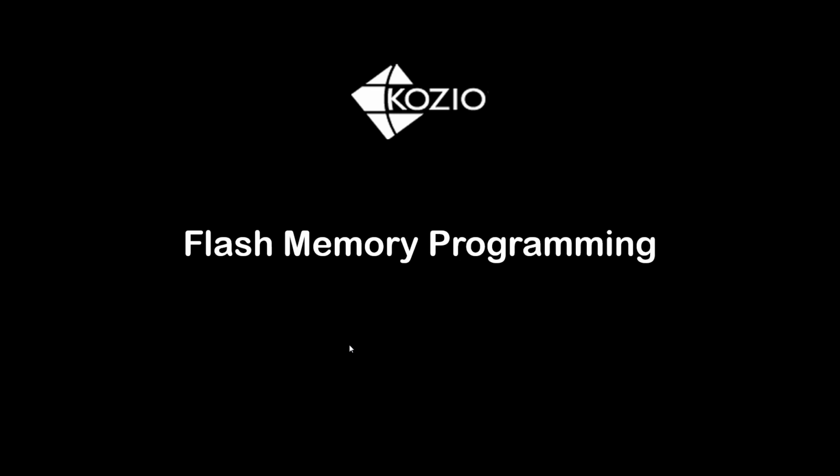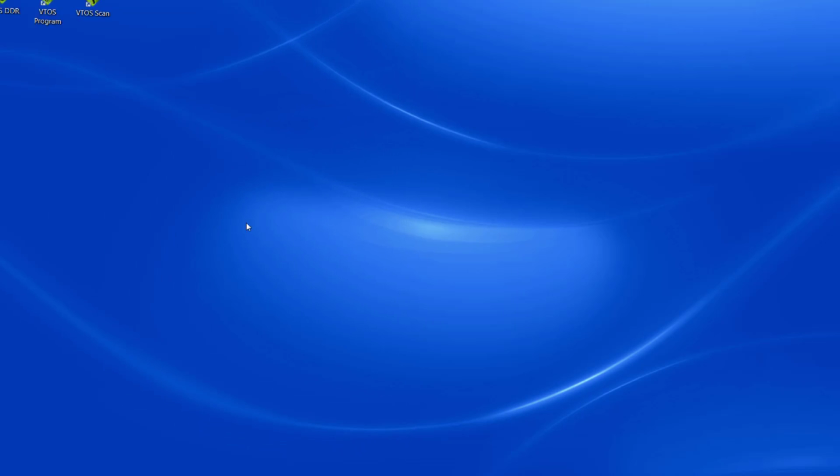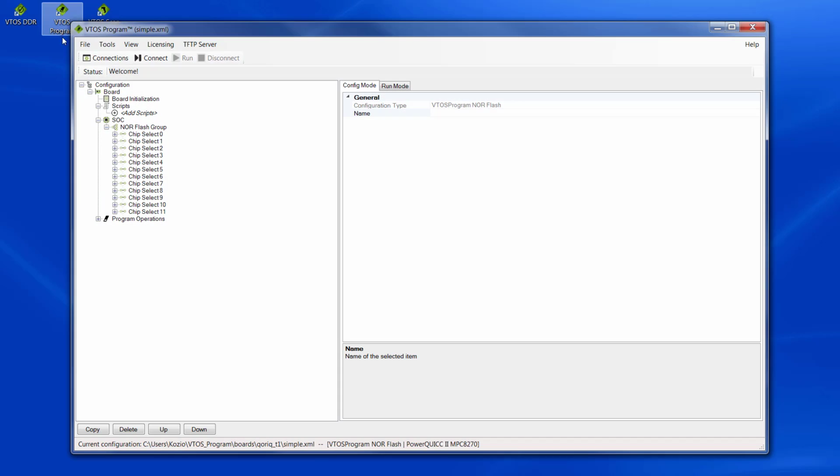In this short demonstration, I'll show you how to use Flash programming software from Kozio to easily erase, program, and verify a flash memory device. For this demonstration, I am running VTOS program software on my laptop and programming the flash memory on a Core iQ T1023 reference design board. I am using a JTAG probe from NXP to automatically load Kozio's firmware, transfer the file, and program the flash memory. Let's get started by launching VTOS program.